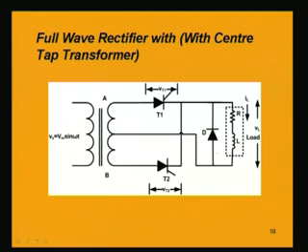So, here we are connecting the diode as we have connected in the half wave rectifier. Here also there is a flywheel diode, and the load is of course an inductive load or a complex load, R and L in series. So, the voltages across these thyristors are assumed to be Vt1 and Vt2, and we are applying a sinusoidal voltage Vm sin omega t. So, in the positive half cycle of the input signal,